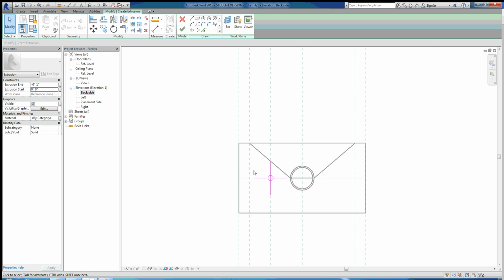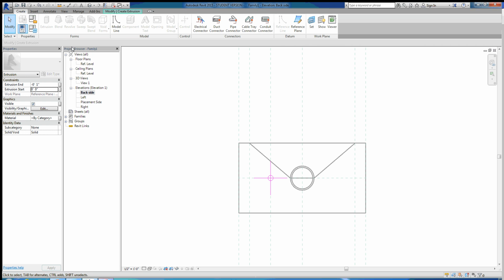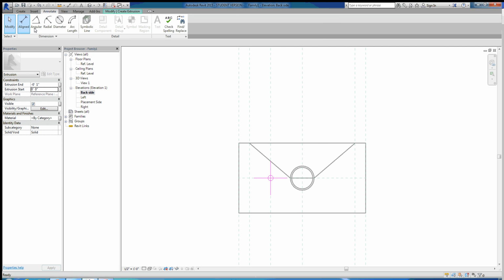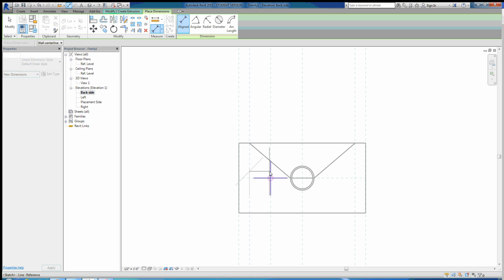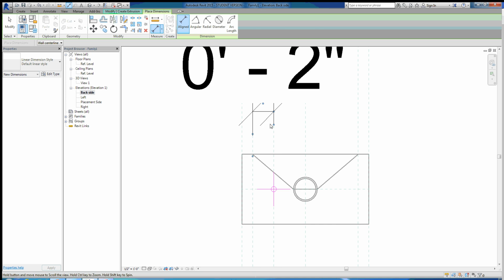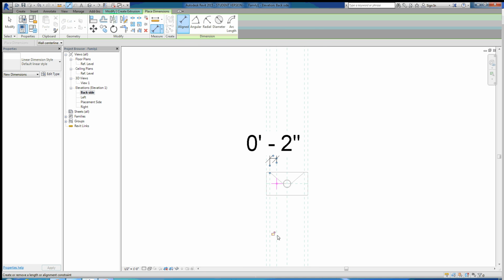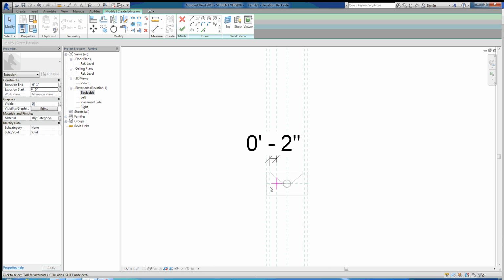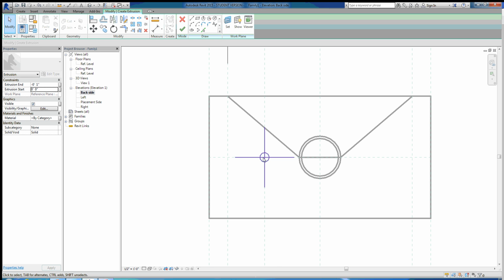And then what we can do is create an annotation from there to there and lock that dimension. So we'll go create, annotate, aligned. We'll go from this to the center line there. Again, it's showing us that it's 2 inches, and we want to lock that. Cool. So that's just going to force this circle to be 2 inches inward from the wall there.